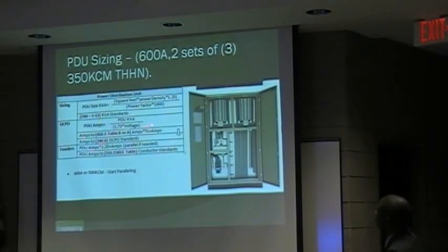And when we go to the overcurrent protection device, we made use of the code book 450.3 B or A, depending on the one that you're going to use, which is going to give you the percentage there. And I believe this one gives us 250%. So we are going to multiply the value here by 2.5.